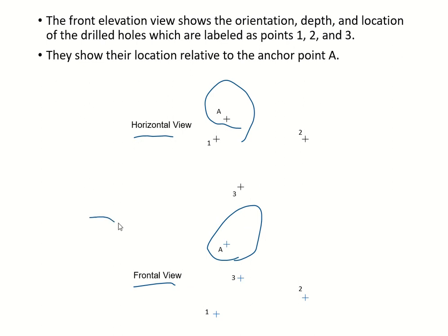I don't have to draw this full line here. Just suppose this is a straight line, proportionally. Remember your extension lines right there. You extend right here, here, here. Those are your projectors, corresponding to each other. The only thing is this one, that's just when you flip your top view to the front like that. So please practice.